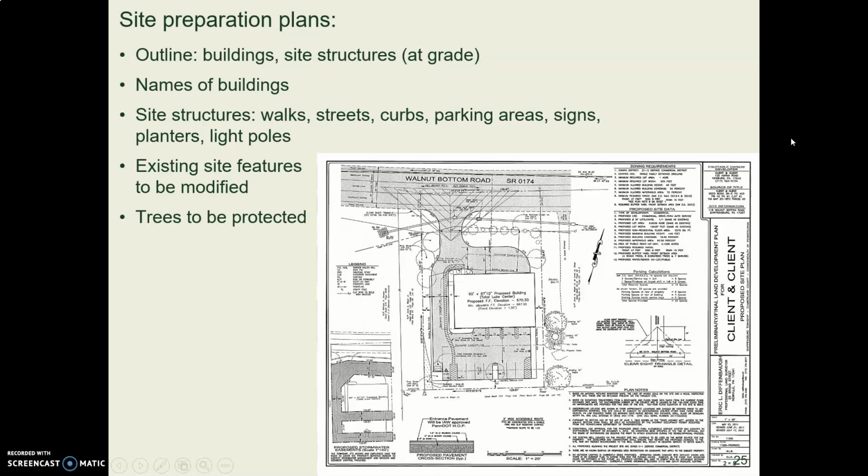In a site plan, it is really important to have a soil protection plan and a tree protection plan. And I didn't want to take the time to go off on a tangent and show you what's in those, but I will just say the basic idea is if you drive heavy equipment over some soil, the soil will be compacted and you won't get it back again. You can do some restoration work, but it will never be the same. And if there are tree roots there and you compact the soil, you can wind up killing the tree over the next 2 or 3 years.